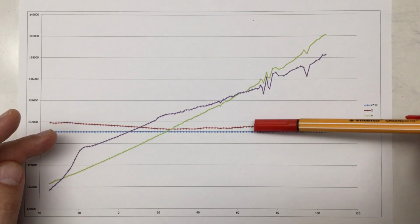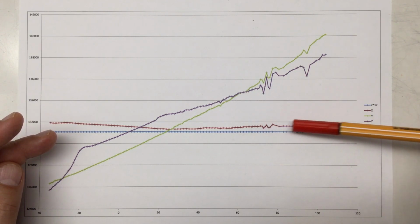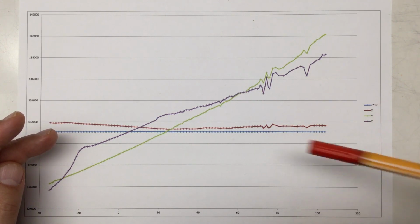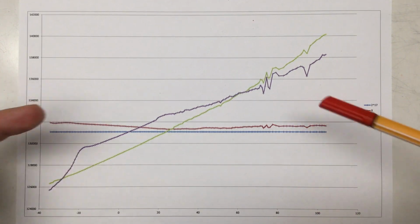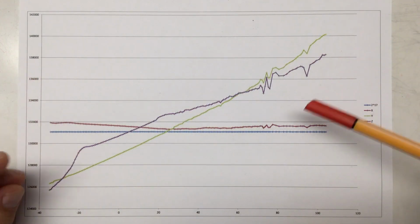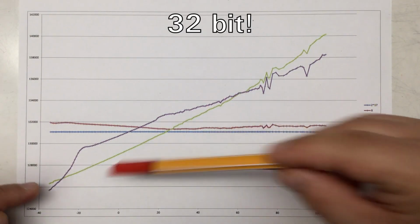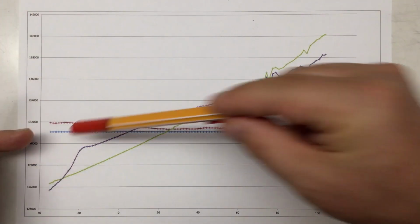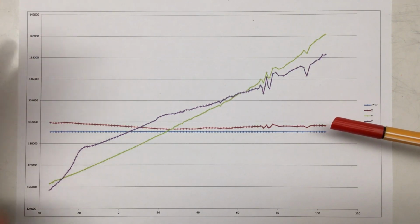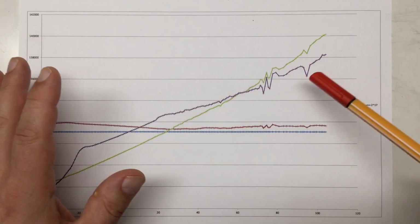And by the way, when I heated up the thing with the heat gun, I was a little bit too fast here at the end, so we don't have a tick really for every least significant bit. Anyway, for real temperature compensation, we would have to store all this data somehow. And we wouldn't need a 30-bit integer here. I mean, these offsets, if you subtract the 2 to the power of 17, would all fit into a 16-bit integer, so easily plus minus 32,000, no problem.